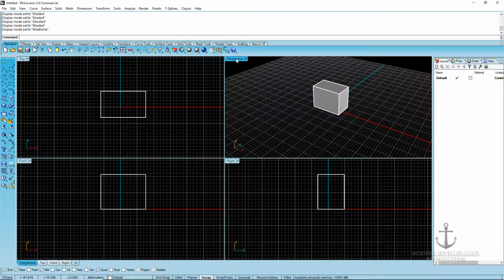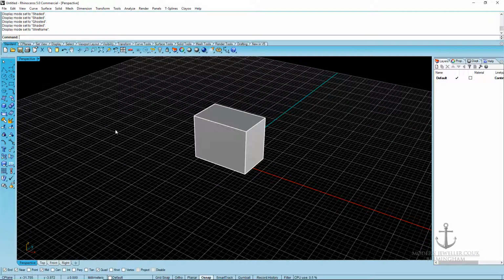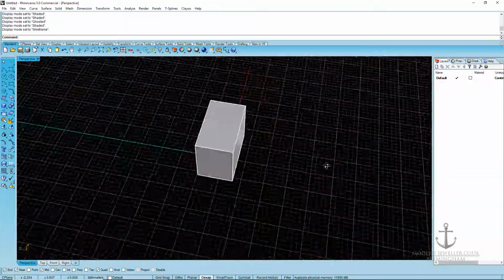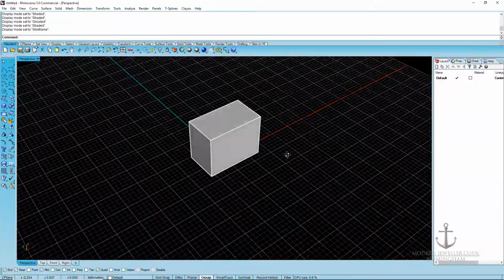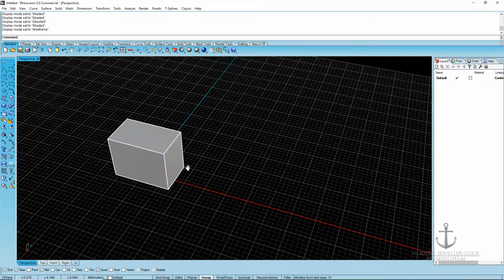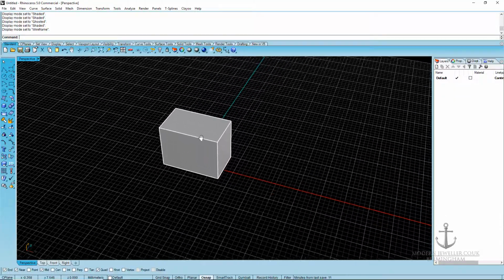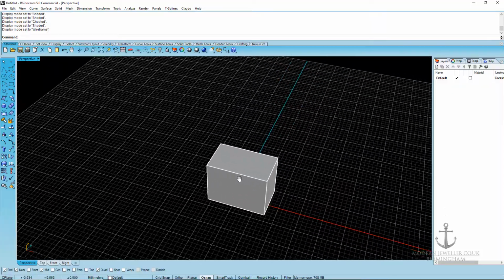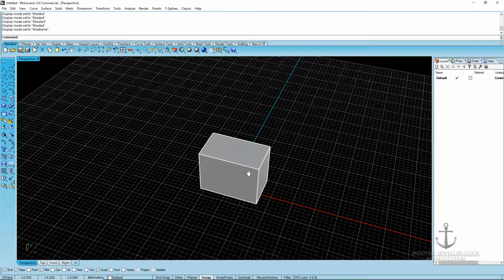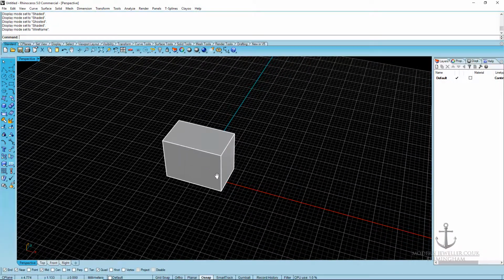Maximize the perspective viewport by double-clicking on the title. Alright. How can we move and navigate the scene? By holding the right mouse button and dragging, you can rotate your view of the scene. By holding the right mouse button and pressing the Shift key on the keyboard, the pan tool gets activated. This command shifts the location of the view camera and target parallel to the view plane.